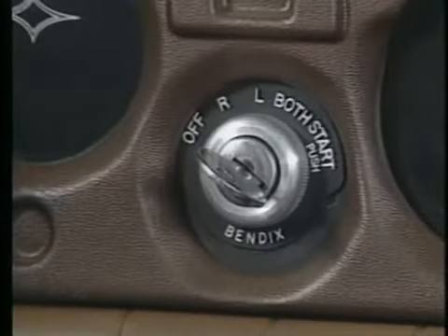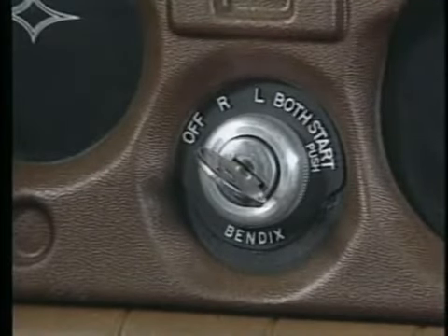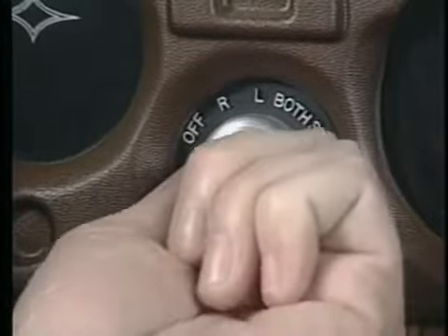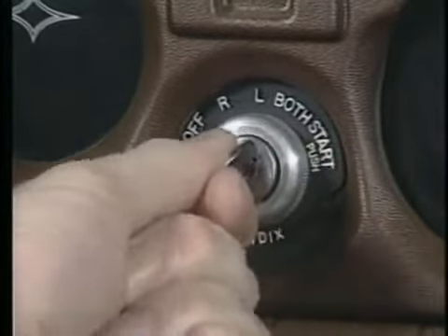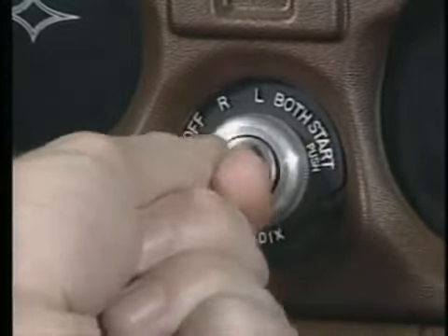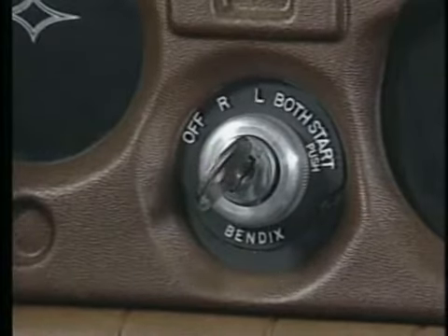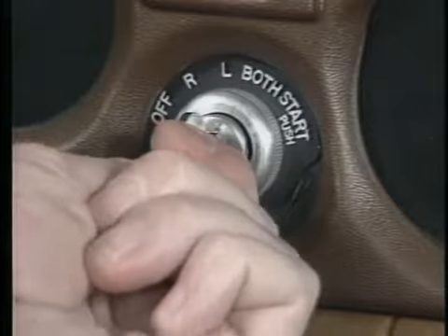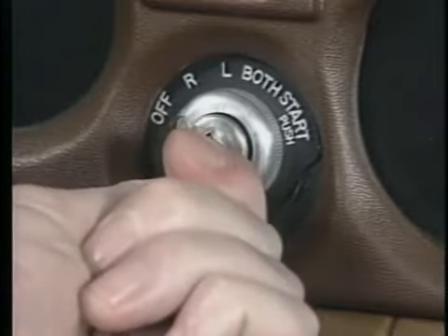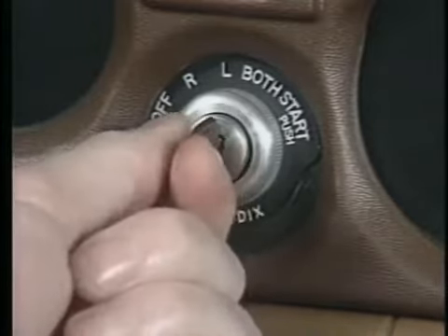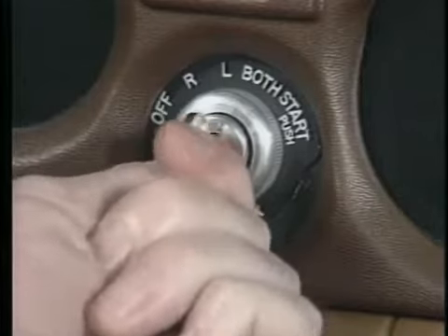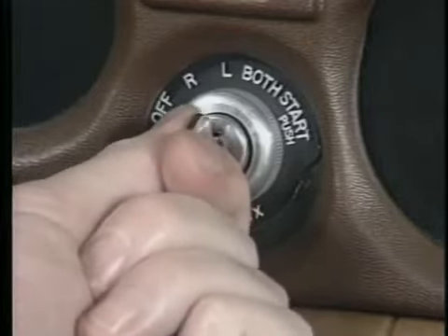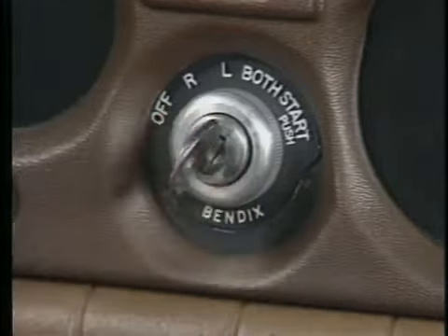The airplane's ignition switch controls which magneto you're using. For example, after the engine starts, normal flight conditions require the use of both magnetos. Before you take off, however, you can test the independent performance of each side. Just how you perform this check will be discussed in the pre-takeoff checklist section of takeoffs and landings.